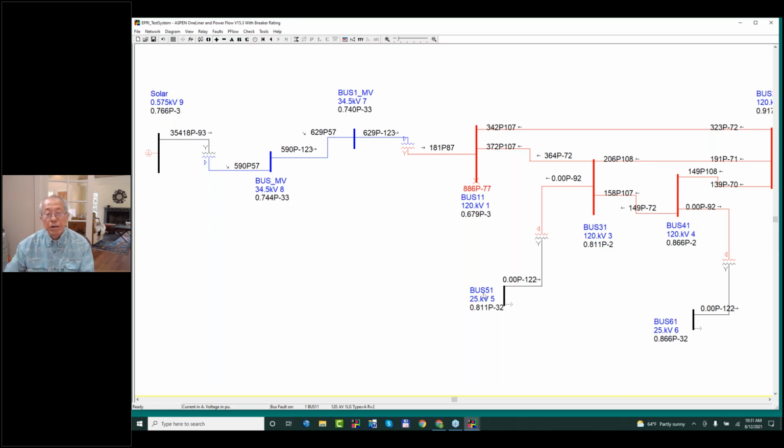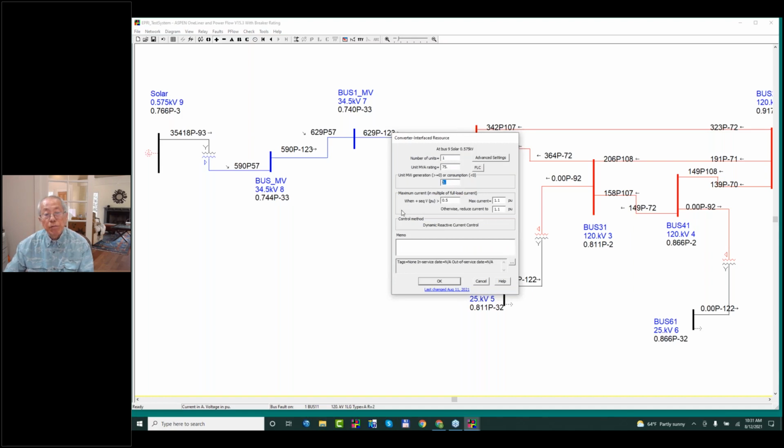Now, if you don't model any loads in the system, why would you model a non-zero megawatt output for your generator? Okay. Now, if you have 1,000 buses and you're only putting in one of these, it doesn't matter how many megawatts you put out. You wouldn't see any difference whatsoever. But if you have a network in an area that already has a lot of these gadgets and they're all putting out megawatts or maybe even gigawatts, well, that's going to have a profound influence on the current flows, and that also affects your relay reaction. And this issue has only been known for a very short time, because everybody's learning from this.